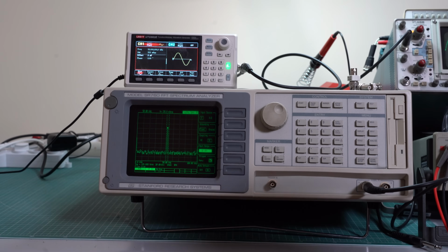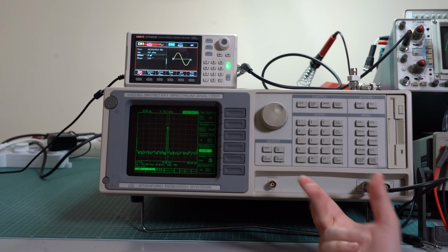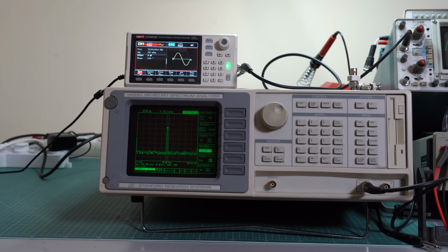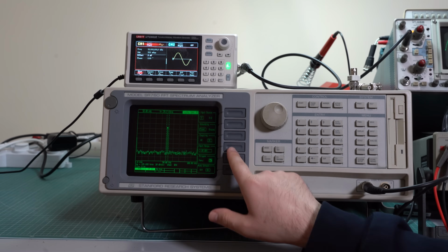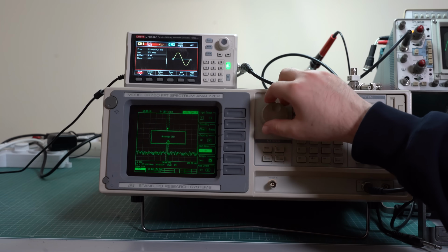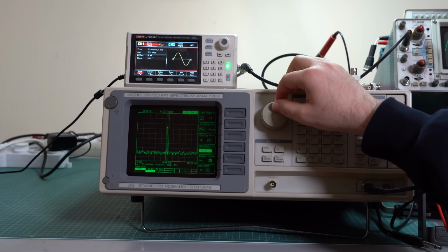One of the most important settings is the input range, which is basically the sensitivity of the instrument. Once again, if you know you're applying a high power signal, don't set this to maximum or you can blow up the front end. So just set it to minimum sensitivity and work from there, I guess. In this case, you can adjust it from the input menu, select the input range, and you can manually adjust it like this. It says that auto range is off, which is okay.